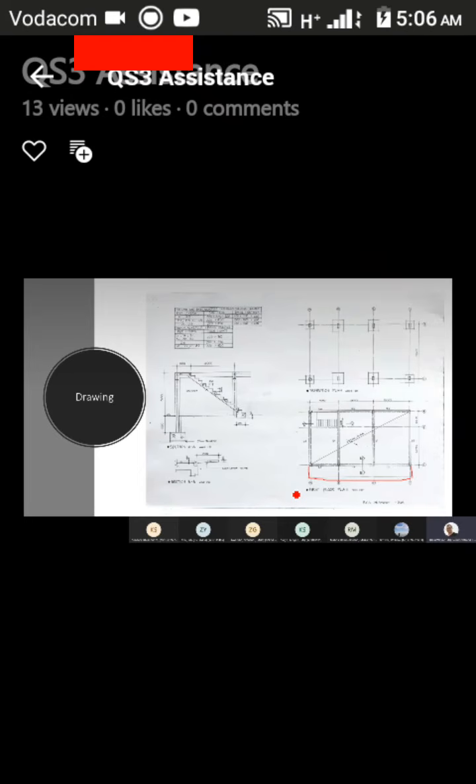You'll see my description says not exceeding 300 millimeters high. Because the thickness on one side is 150, the other side is 100. So it will fall, and the standard system tells us that when it does not exceed 300 millimeters high, it will be measured in meters. So it will be measured in meters, and I have 14.22, which is that, and then I have 1.5, that, and that. So there's two of the 1.5.